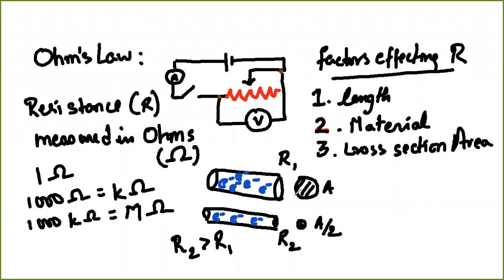So if you want a larger current to go across, because these are larger devices, they need more electricity, more current, so therefore their wires would be made thicker. You cannot put a large amount of current through a small wire, because the wire would then heat up because of the higher resistance, and a fire accident is possible. So that is why they use wires with larger cross section for devices which use a greater amount of current. I hope I made that point clear. If there are any questions, you can ask about it.